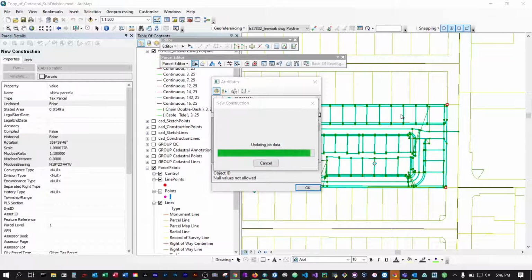So once you paste the subdivision or the plan or the CAD lines, before you actually create join links and then join this to the parcel fabric, you would want to select those lines manually and delete those specific lines that you don't want.